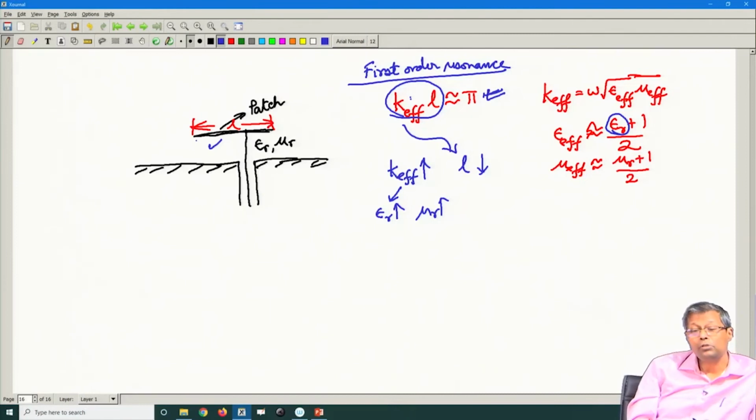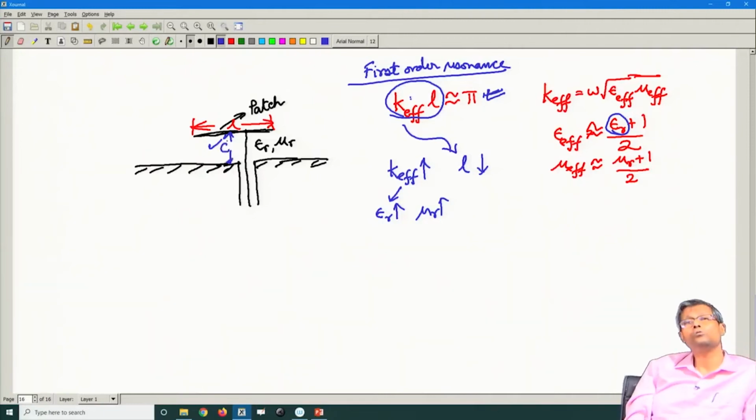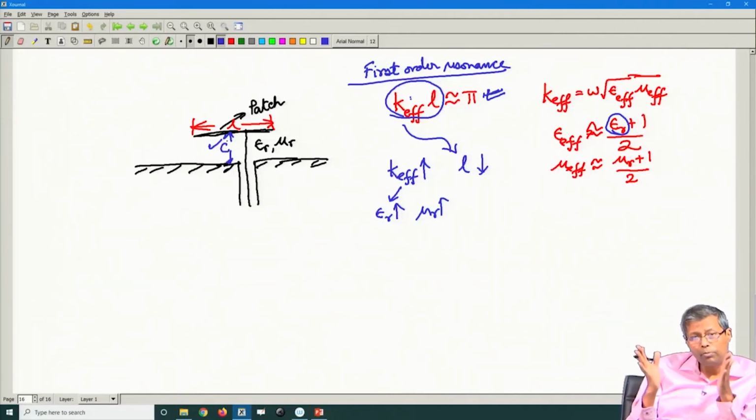Additional to that, we have to see how this antenna radiates. For this antenna, you have to first look at the phenomenon that the microstrip patch is inherently a bad radiator. Why is it a bad radiator? Because it is inherently a capacitance. There is a capacitance formed between these two metal plates. A capacitor does not radiate, it tends to store energy. So, as you try to make the microstrip patch smaller and smaller in size, this capacitive effect will dominate and will pull down your radiation efficiency.